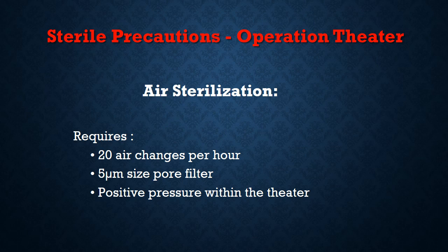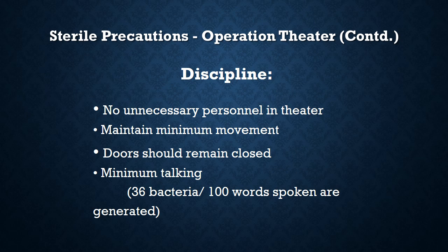Plus, another factor is that positive pressure ventilation is maintained within the theater so that the air is flowing out of the theater into the galleries and the other OT complex and not being sucked from the galleries into the operation theater. Then you have to maintain a certain discipline in the operation theater.